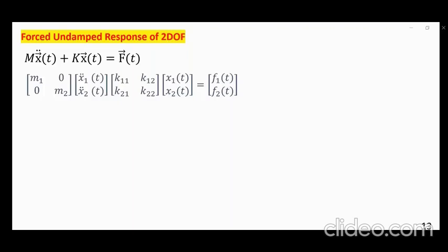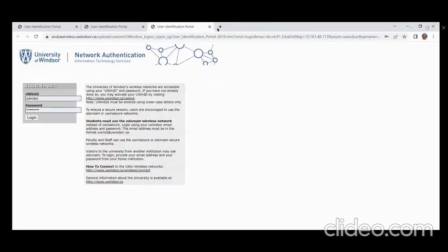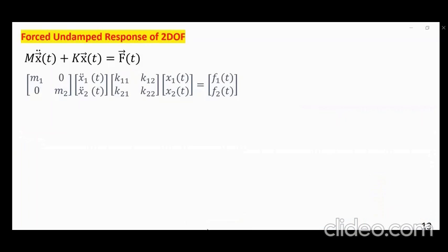However, you will see that irrespective of that, when you use modal coordinates, in other words, when we do that transformation going from x to q, then the resulting mass matrix and stiffness matrix will both be diagonal. But as it is, the mass matrix is diagonal to begin with, and that's because of the way we have handled the course so far.